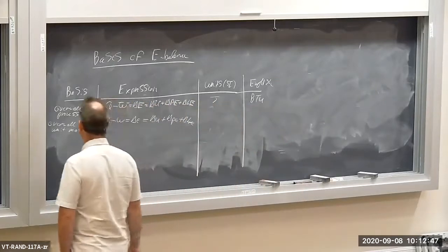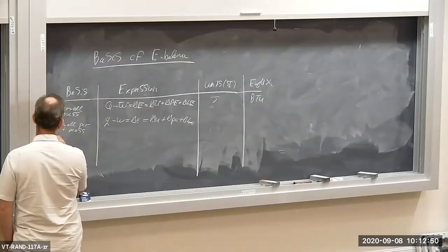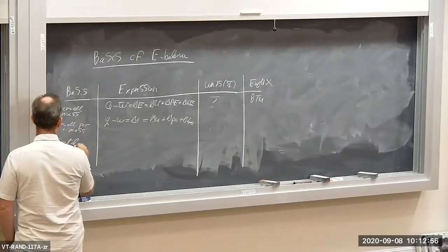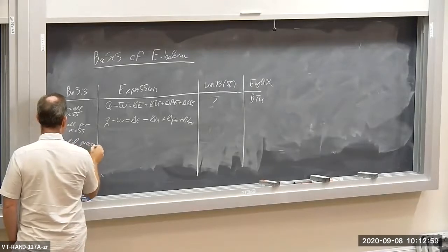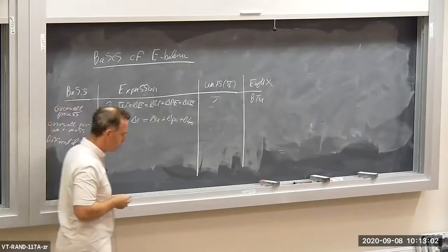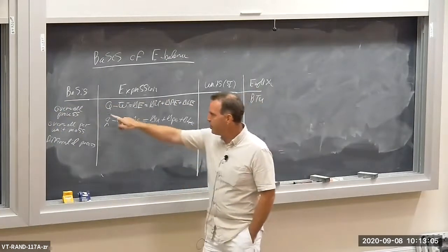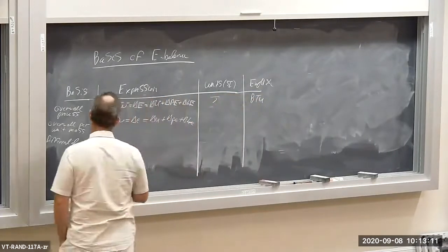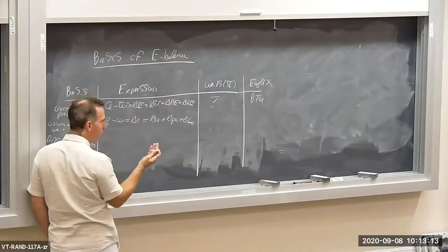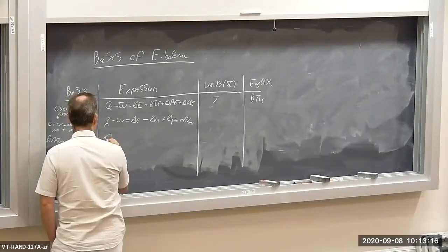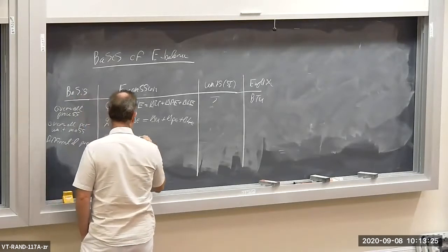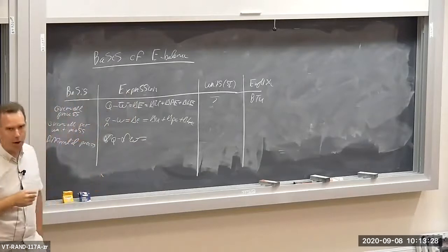There's also the infinitesimal or differential process. So differential process. If I take the derivative of this equation, or total derivative, if you like, I get a little bit of heat transfer, del Q, minus a little bit of work, del W. Remember, work and heat are path functions.